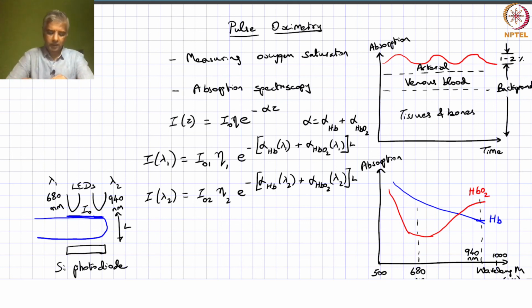It's because when you illuminate, you can maybe focus your illumination in a particular direction, but once it goes into the finger, the tissue will tend to diffuse that light in multiple directions. So if you have two different detectors, there will be crosstalk with the other detector, not just the detector that it's supposed to go to, but the other detector will also start picking up.